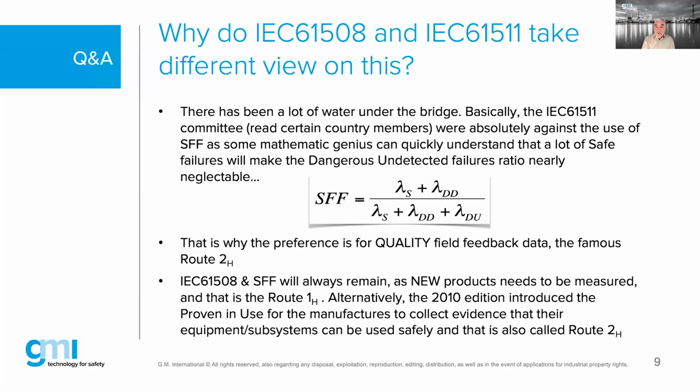It's about time, Mr. End User, since the year 2016-17, so it's 10 years now, that you start to collect your own data, which is a great story for an existing plant. But what do we do with a greenfield where we start from scratch? How do you get your data? Well, that's again going back to the 61508, and that's where we again have to trust, believe the safe failure fraction.